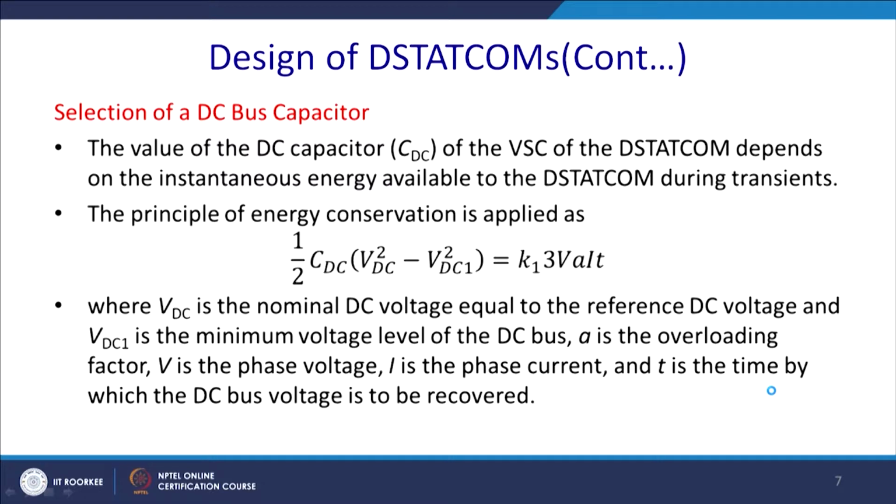The value of the DC bus capacitor C_DC of the VSC of the STATCOM depends on the instantaneous energy available to the STATCOM during the transients. The principle of the energy conversion is thus half C V squared.